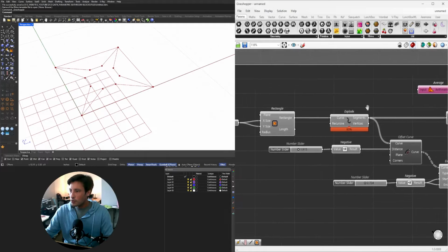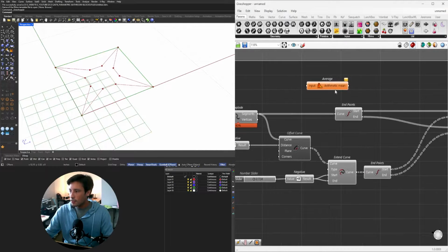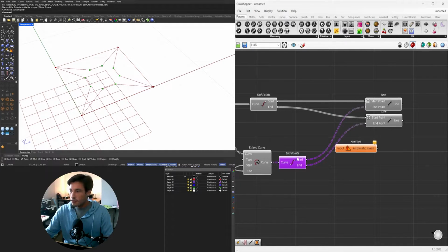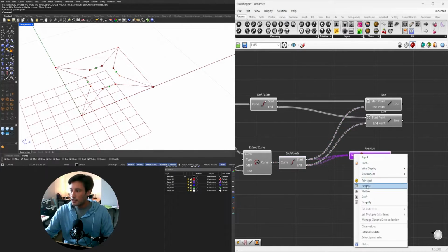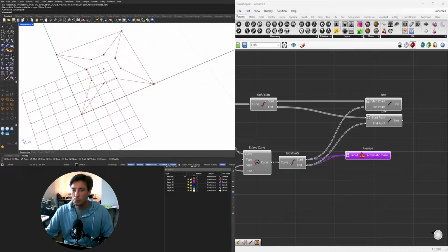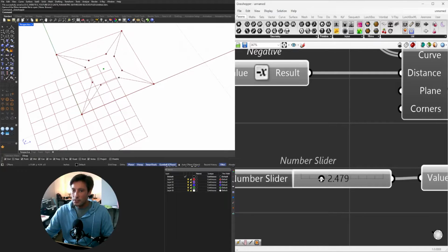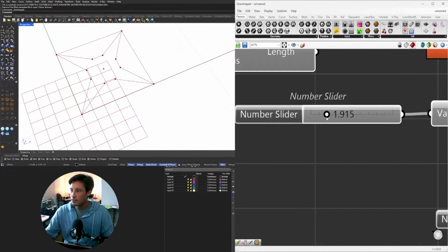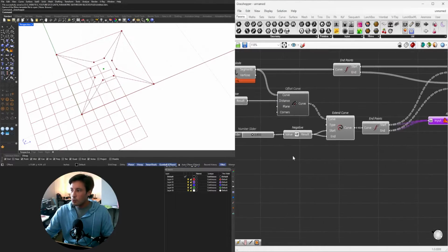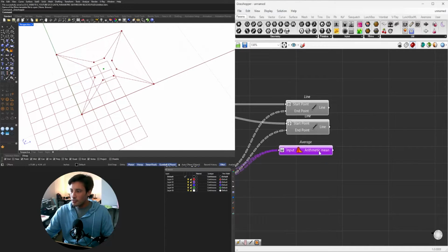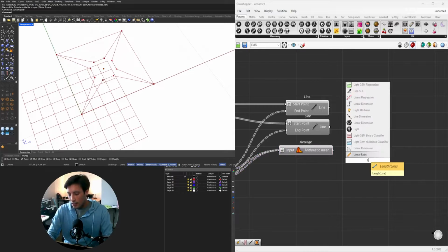So now we can go to, let's say, these points, plug them in, flatten the input, and it will be in the middle because when you average out these points, they average here in the middle and they won't change ever because it's a symmetrical offset. And so with that center point, we can now connect a line segment.